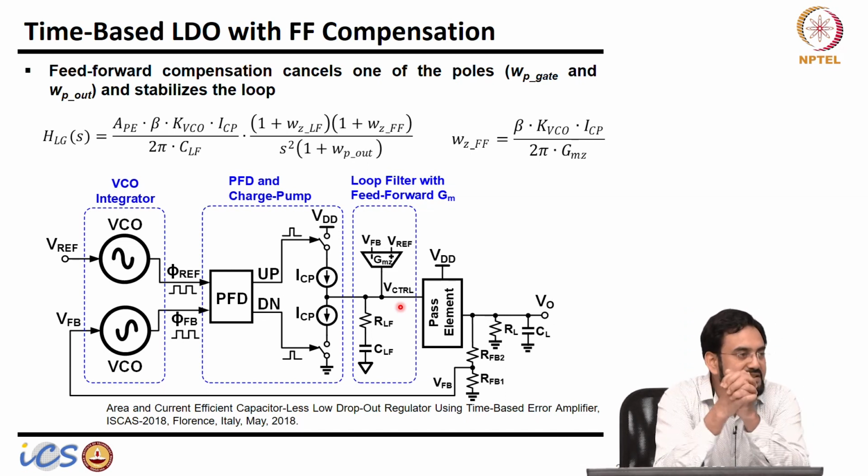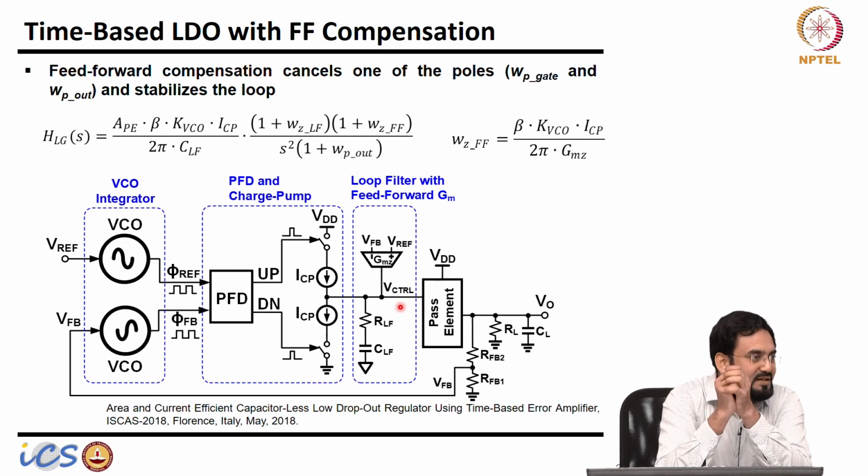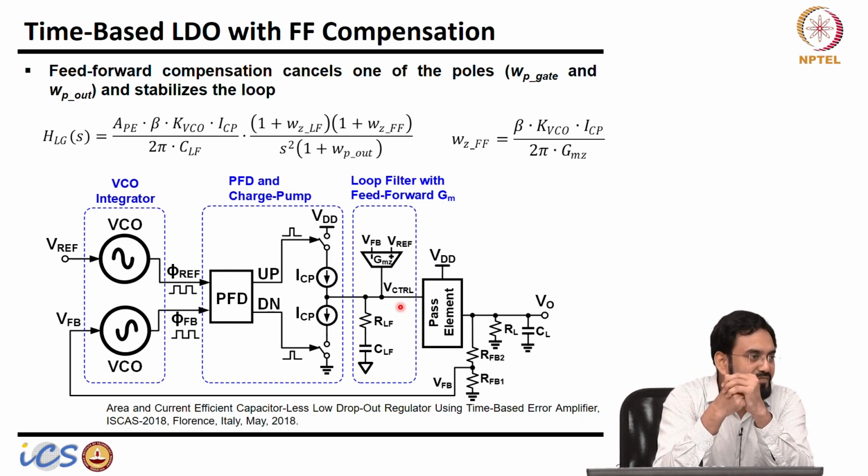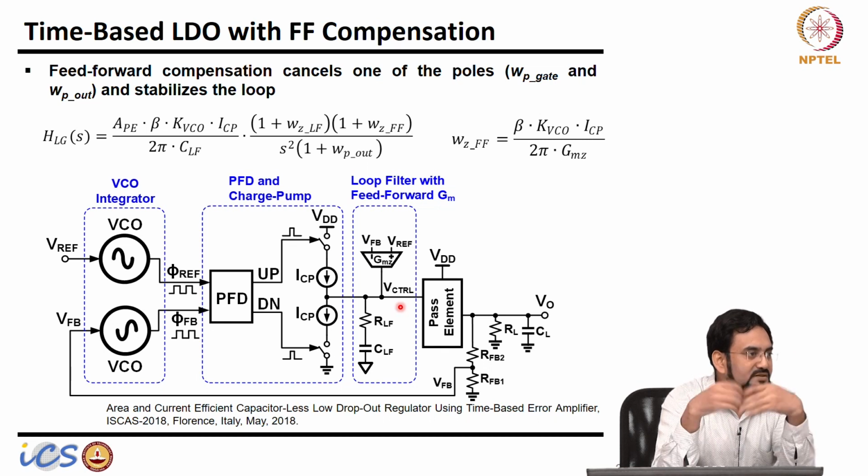So the advantage here is, now the capacitance seen at the gate by each phase is very small. So you can increase the bandwidth without increasing too much current. And another advantage is, look at the light load. If you oversize your power FET, then when you go to very low current, it will go into subthreshold and saturate.